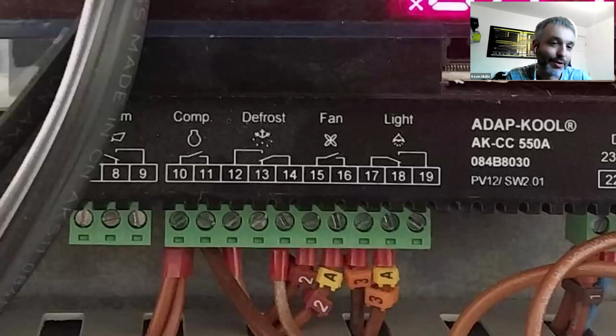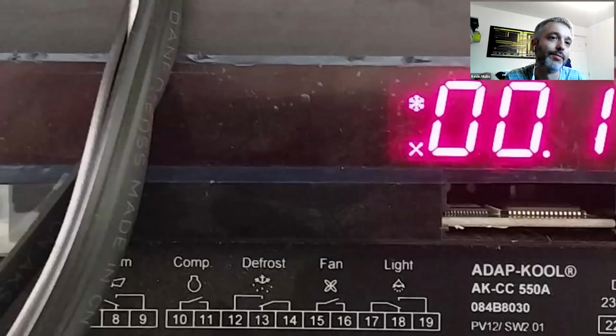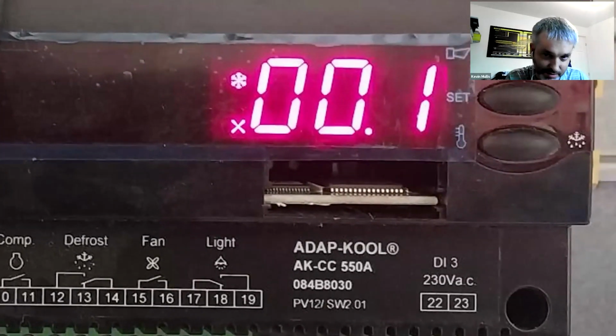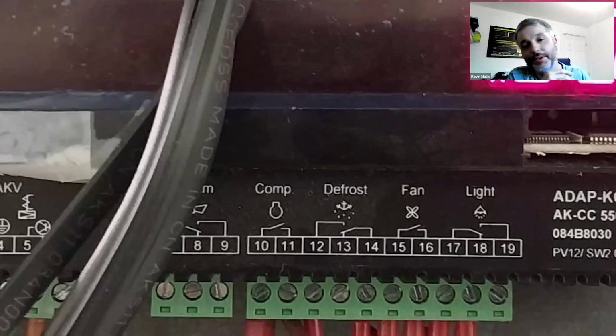So the defrost, if you've got electric defrost, you will almost certainly find through a contactor. Again, if your case is iced up, put it on defrost. If you push the bottom button on the controller and hold it down for 4 seconds, it'll go into defrost. And you should then see the defrost relay close. And you can do some tests from there. Have you got an output on the defrost relay? Is it pulling in the contactor? Are the heaters working? Etc.